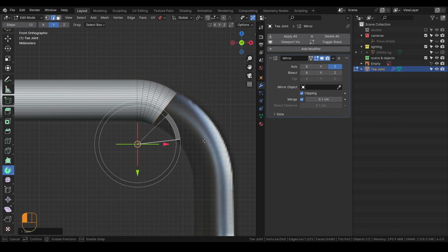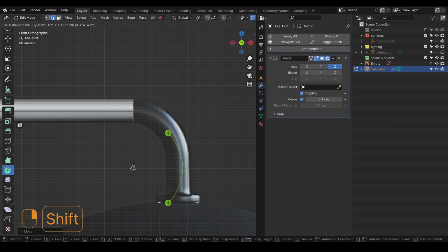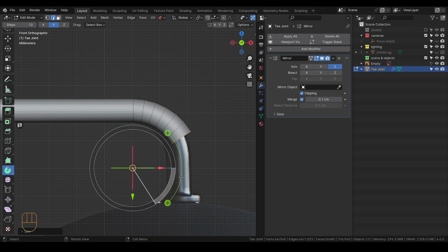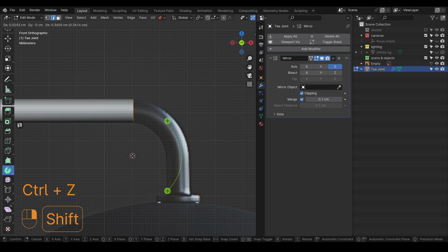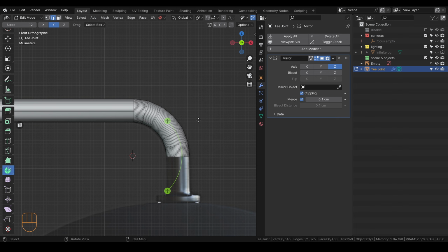As you can see, this is not going to match the reference, so we can try again. And I will give you a little tip. You need to try to put the cursor on the same axis as your edge loop here. So somewhere on this line here. And I found that this one roughly matches the reference. Maybe up a little bit. Yeah, as you can see, this one looks good enough. You can also press Ctrl to do increments. Maybe I'll stop here. Okay, this looks fine.